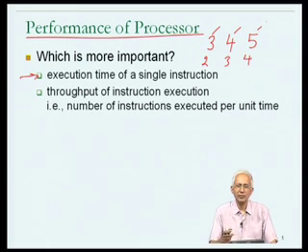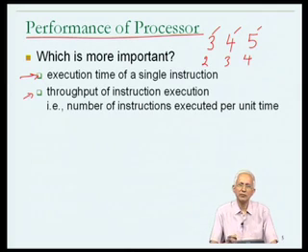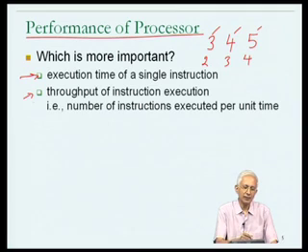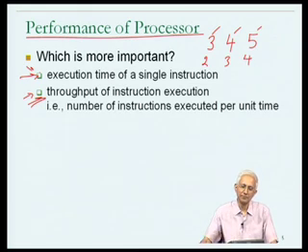The manufacturer of a processor knows that the processor will sell well if it is able to execute programs faster than the competitors. Therefore, whichever of these objectives will achieve that ultimate objective is probably the important one. And with a little bit of thought, one can actually argue and convince people that the throughput is where one is going to get faster program execution, not necessarily from the faster individual instruction execution time.